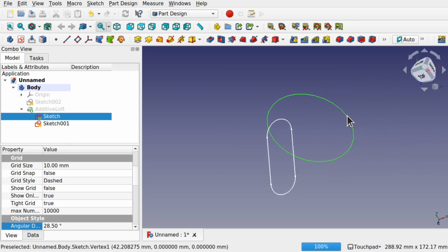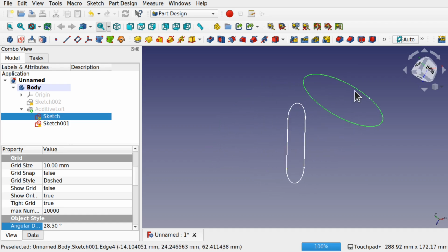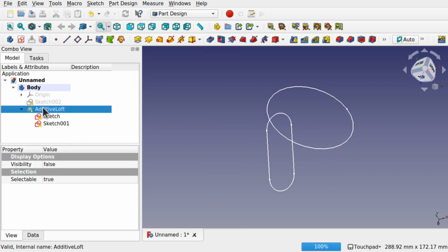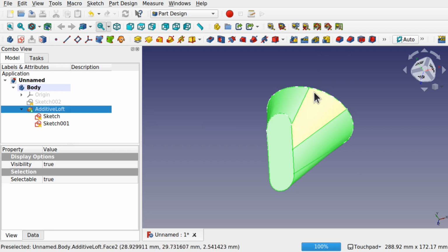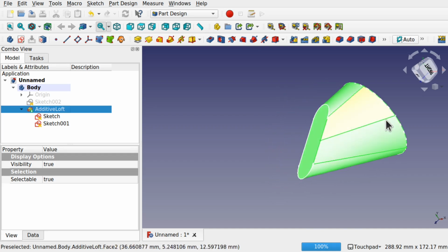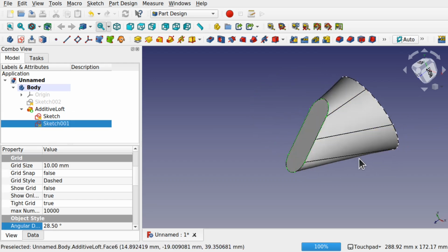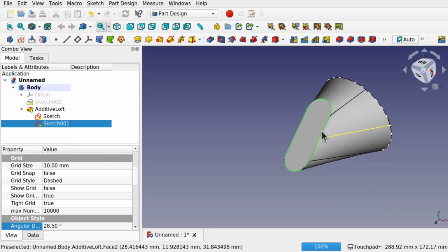But that vertex, when it's lofted through, will attach to here because we make a hybrid between these. If I took this sketch and added, say, 2 arcs, then we get a different effect. So let's have a look at the Additive Loft. You can see those vertices. We've made a blend between those vertices. So there's 5 vertices altogether because this one was out of place.